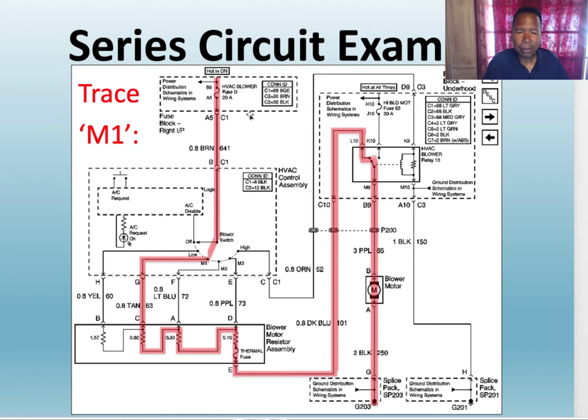Here's a great example. I got voltage here, and using the wiring diagram, you start from top to bottom. It's my source. Arrow here says come from the source, which is probably the ignition switch or the battery. My fuse, which is, let's say for the example, 12 volts. 12 volts going through this fuse and out this wire. Circuit 641 from connector C1, pin A5, brown wire.